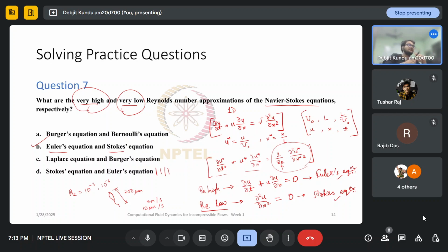So just on a side note, Euler's equations, if we integrate them, we get the Bernoulli equation, which we learned in school and maybe in the basic fluid mechanics course in bachelor's as well. They are very important for solving pipe flows and things like that, for designing pipelines of a building or a chemical plant.